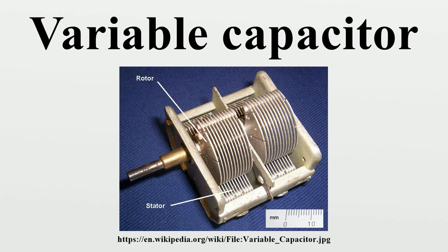Electronically controlled. The thickness of the depletion layer of a reverse bias semiconductor diode varies with the DC voltage applied across the diode. Any diode exhibits this effect, but devices specifically sold as variable capacitance diodes are designed with a large junction area and a doping profile specifically designed to maximize capacitance.